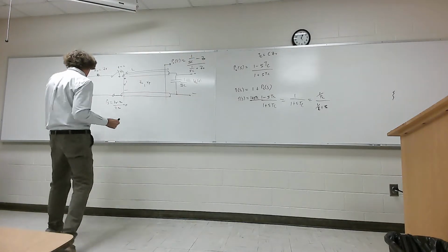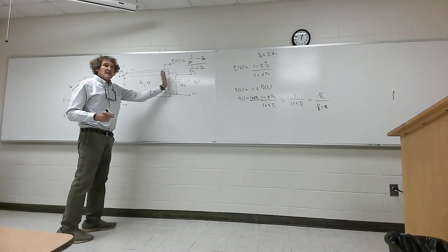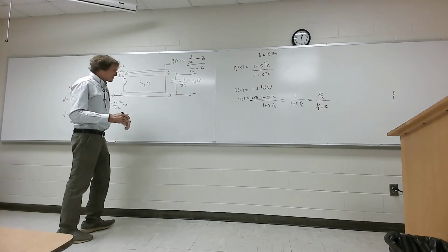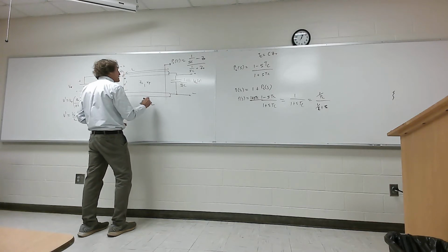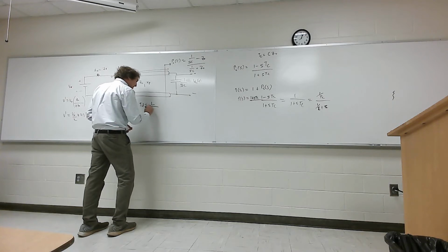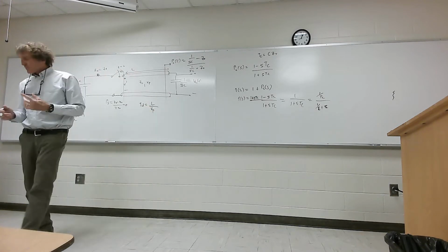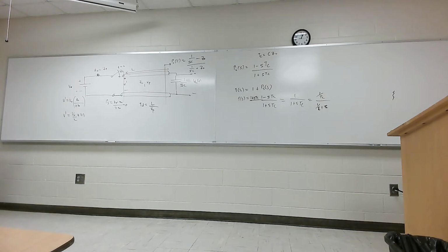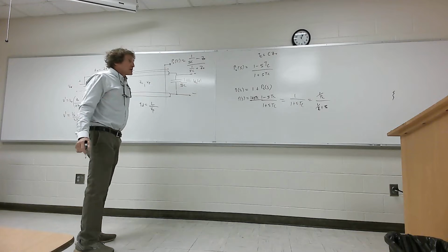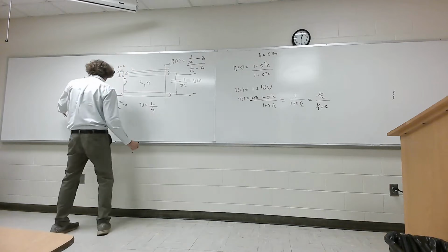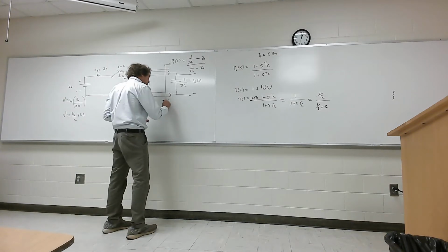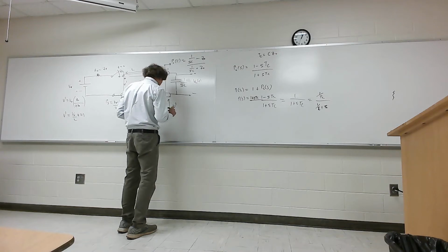Now, that takes a certain finite time to get down this length, right? After the switch is closed, and what do we call that? I call it the delay time. That's simply the length of the line, whatever that length is, divided by the velocity of the wave. It's really the velocity of the electromagnetic wave on the transmission line. Follow me? Y'all remember me doing this before, right? So there's really only one thing new, and that's this. So now we take a look at that. And that means this V prime will impact here, and the actual signature there would be V prime, or really, I'll call it V naught.